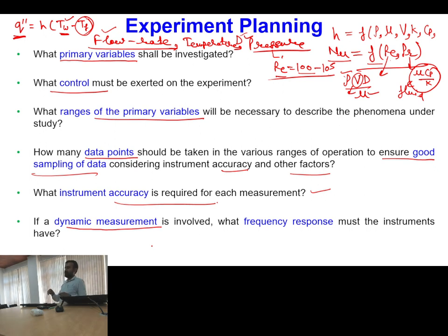In a steady state experiment, you run the setup, allow it to reach steady state, and at steady state you just want to measure your data point. The second requirement can be that you want to know what path the system takes, how it behaves, when moving from its initial condition to steady state. Then your measurement will actually be dynamic. Time dependent measurement is dynamic.